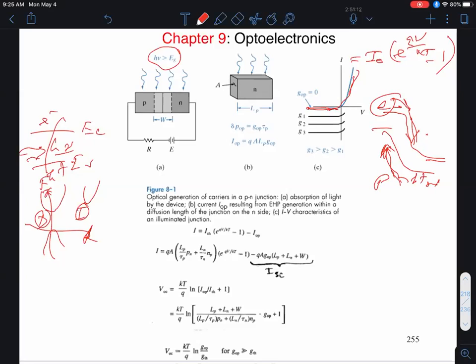But now I can increase that supply by shooting photons at it with an h nu greater than the band gap. So now I create extra electrons and extra holes, and therefore the supply is increased. Therefore, your effective leakage current goes up, as shown over here. So with increasing photon fluxes, you can get more effective leakage current. Okay? And if you operate in that mode, that's what a photodiode or a photodetector is. You basically get an electrical signal which is proportional to the light intensity, which is obviously a very important application, right? You can convert light into electrical signal.